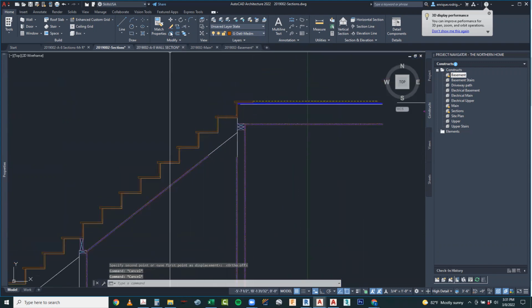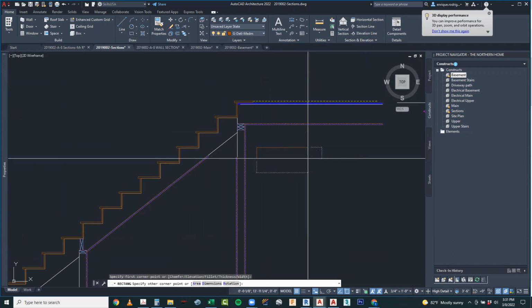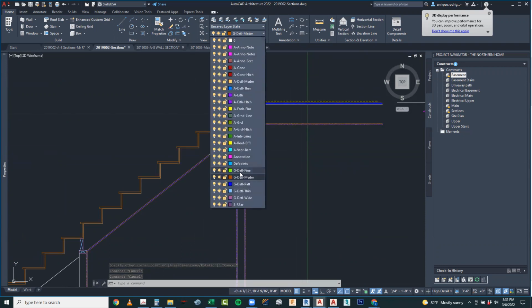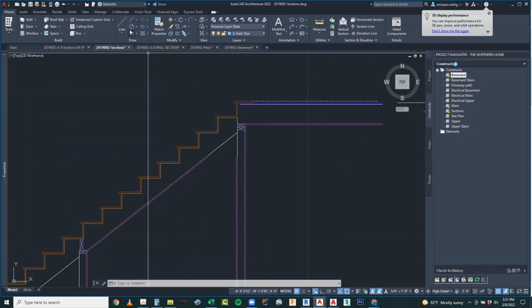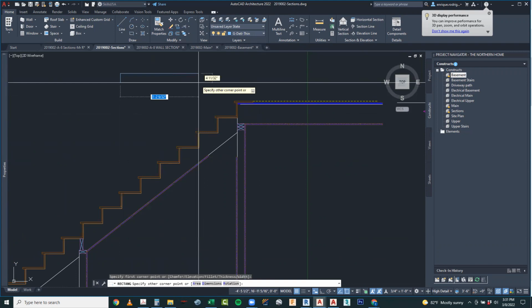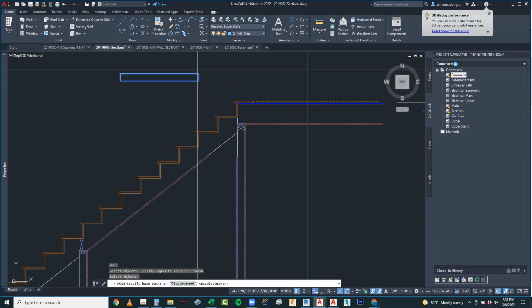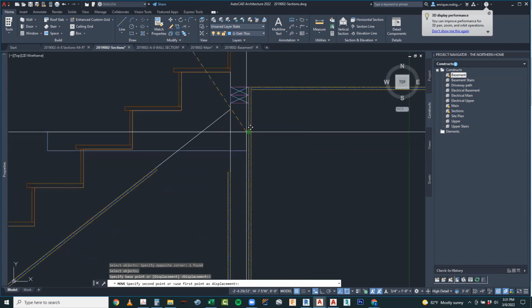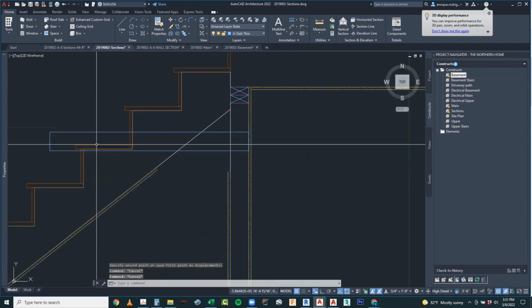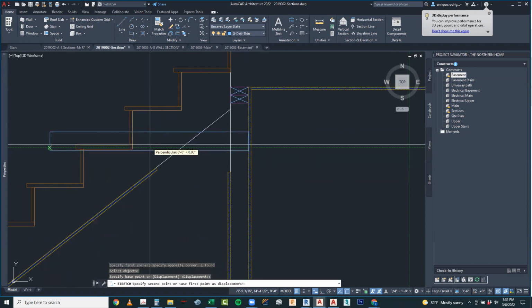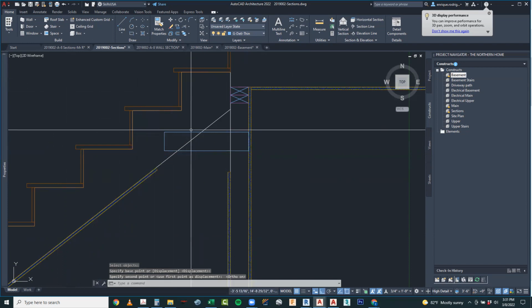All right, I'm going to go ahead and draw my kicker there, which is just going to be a 2x4. It's not going to be in section, so I'm going to use a different layer. Let's do G detail thin. Rectangle. The length doesn't matter. The height is going to be 3.5. And I'm going to place it right here. It's going to get nailed to one of the studs there. And then this side, put my ortho back on, gets nailed to the stringers.